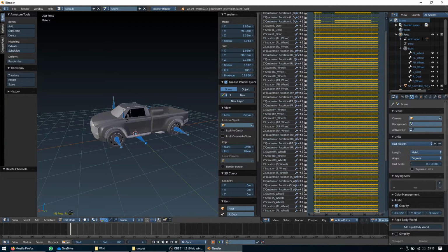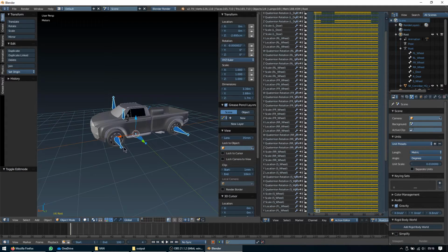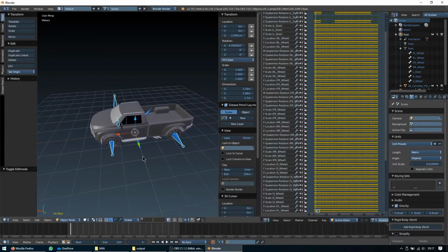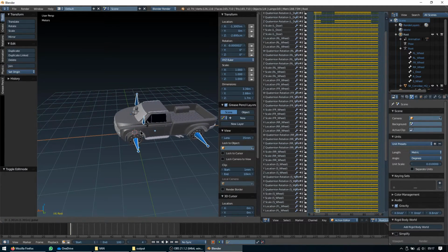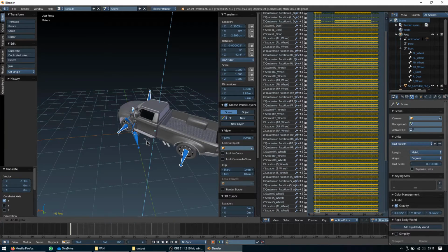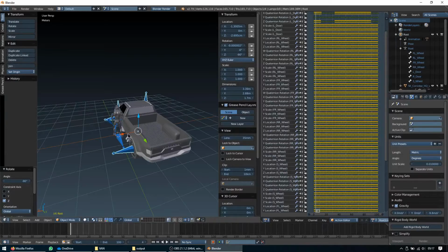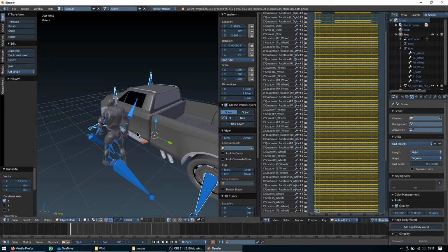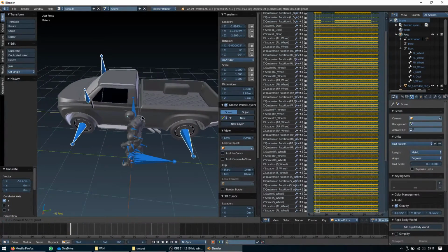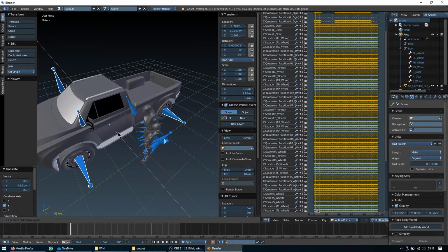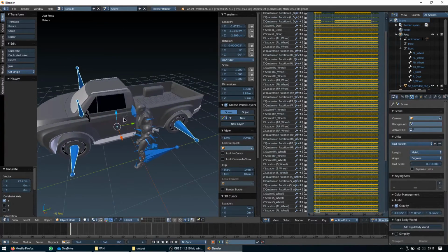Okay, now go to object mode. We can now edit our location and rotation of the root object. So type here -90 and bring the vehicle something like here. If you play, you will see they play together.